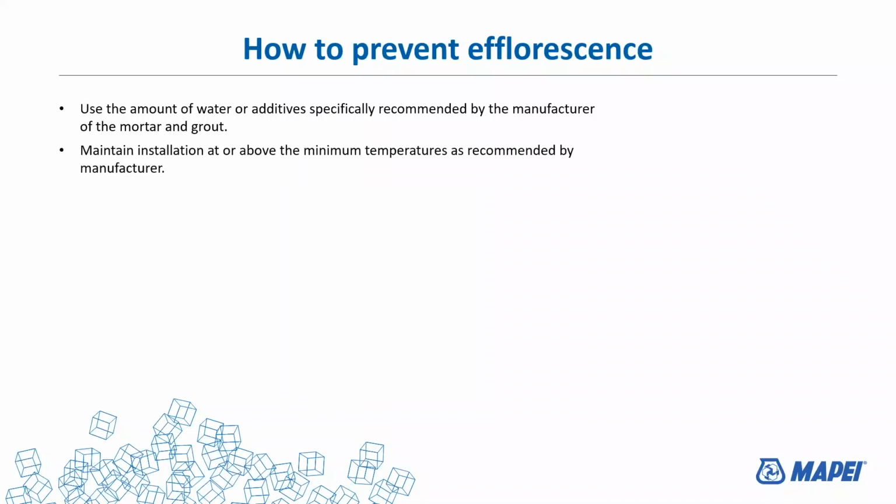Install grout as firm as possible but pliable. In other words, dry but wet. You guys can imagine that. Dry but wet. The people that have been in the business understand it. There is a delicate balance between firm and not. So it should be, if it's mixed according to the instructions for the right amount of time with the right amount of water, you should have that type of a grout mixture when you're ready to apply.